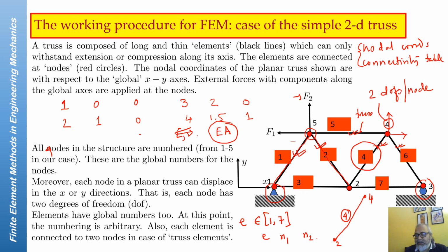The number of property parameters that you have to give for elastic problems is generally small. But for more complicated problems, like nonlinear materials, you might have to give a lot of property parameters. For our cases, for elastic materials, we will generally give only E and nu for each element.